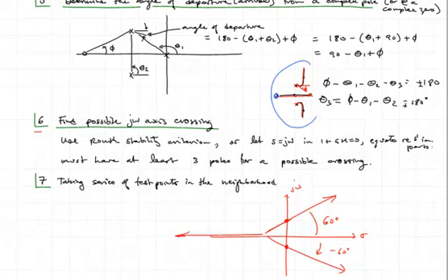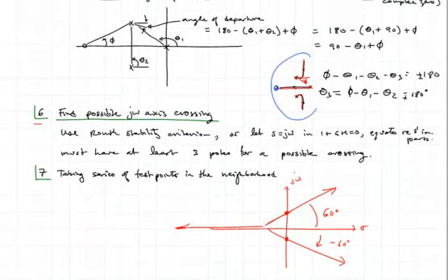Okay, and then we want to test a series of points in the vicinity or neighborhood of the real and imaginary axis and satisfy the angle condition graphically in that vicinity, and that will help us fill out the root locus path along with the information that would have been gathered up to this point. And at that point, you should be able to draw the root locus plot.